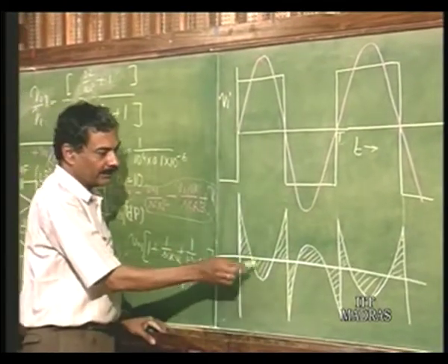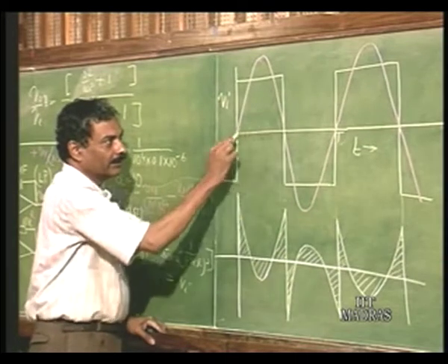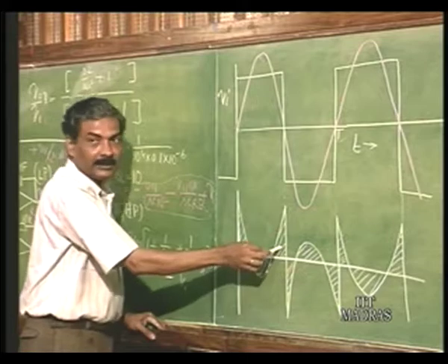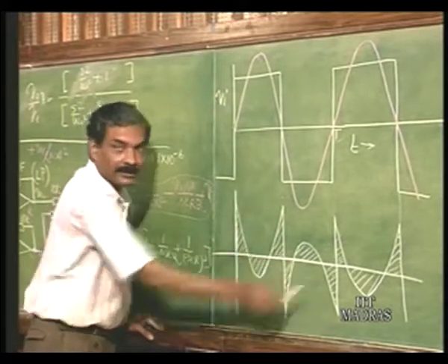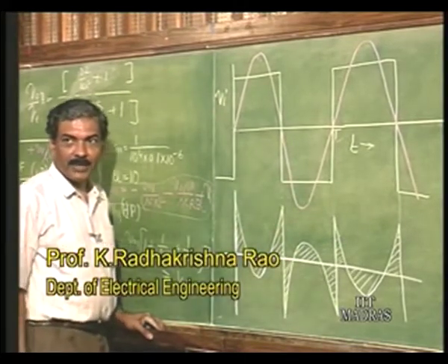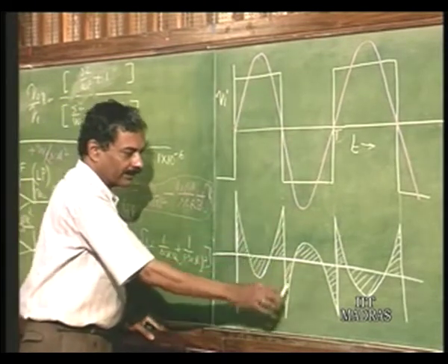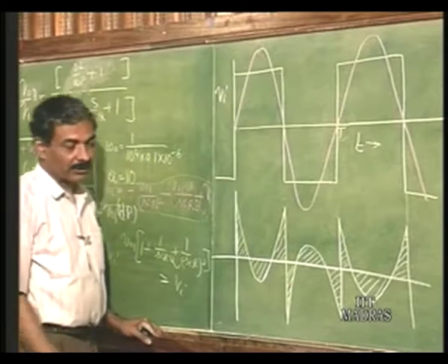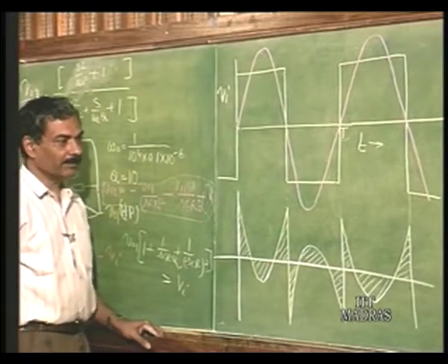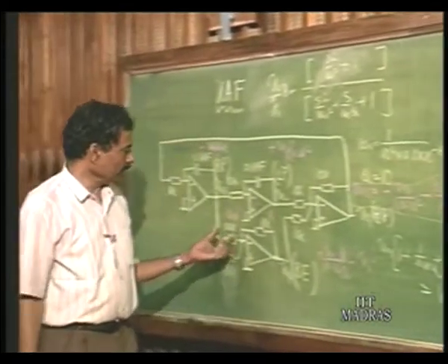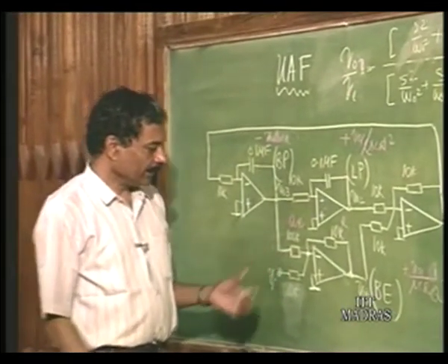You can see that it is third harmonic because in one time period you have 1, 2, 3, and 1, 2, 3. So, it is predominantly third harmonic and higher, because these are not exactly sine waves. So, higher harmonics are also present. This is going to be demonstrated clearly to you. This is a high Q circuit. I have purposely made this Q pretty high here.